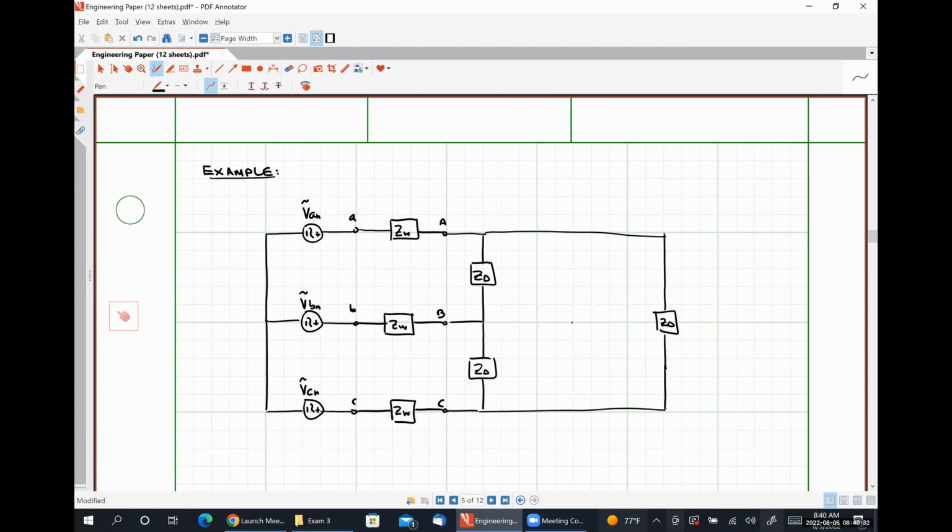This is effectively the hardest type of circuit I could possibly ask you to solve for. The reason is that if we had two Y-connected loads in parallel, we could just represent them as a single Y-connected load by giving an equivalent impedance. Similarly, if we had two delta connected loads in parallel, we could just combine the per phase impedances using simple impedance combination techniques. So we can really represent any combination of Y connected loads and delta connected loads together using this circuit.